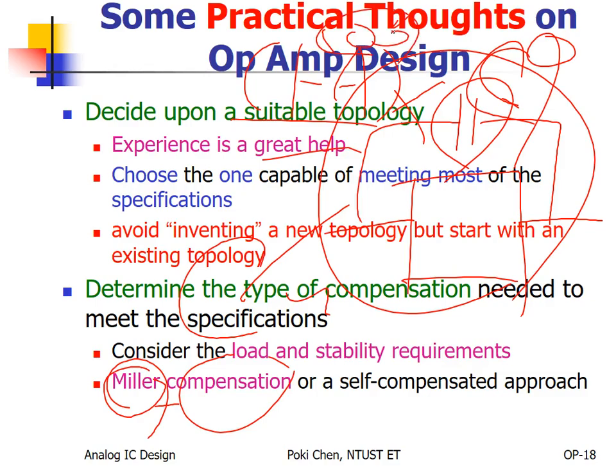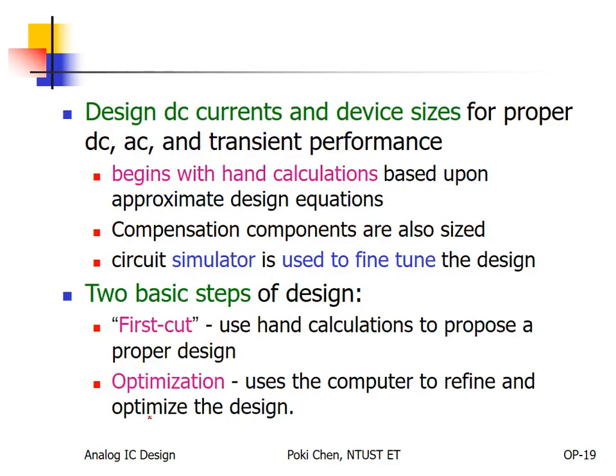The real capacitance can be reduced by 100 times, because it will be increased by the Miller effect 100 times. That's it. So, there is another lesson for you here. Never mind whether the phenomenon is good or bad. You need to know all of them. Sometimes even a bad effect can do you much goodness.